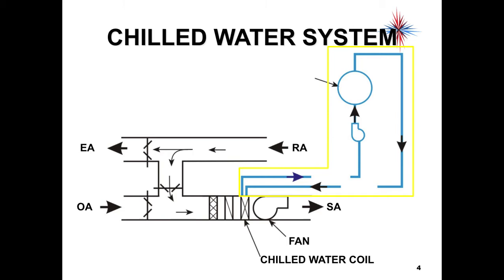Okay, but some additional parts you may want to know about, chilled water return. Again, we're looking at it from the standpoint of the system. So the chilled water return is the water going back to the chiller. Chilled water supply is the water coming to the coil. So again, supply and return, we're always looking at from the system that generates it.